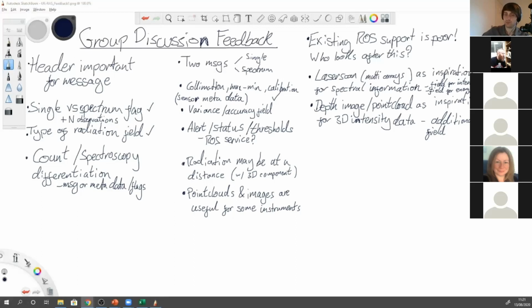Yeah. The question would be whether the robot can physically move to every coordinate in the point cloud and make a recording in situ, or if you want a range standoff kind of measurement where the radiation sensor is mounted on a turret and just scans an entire room, for example, which is a completely different order of complexity for a problem. Yes.